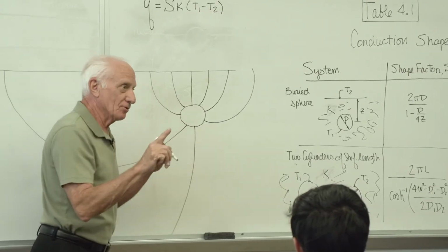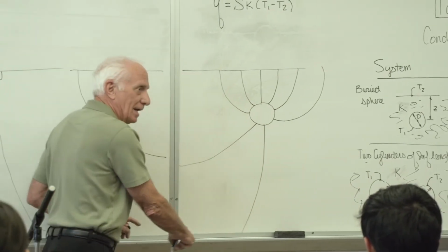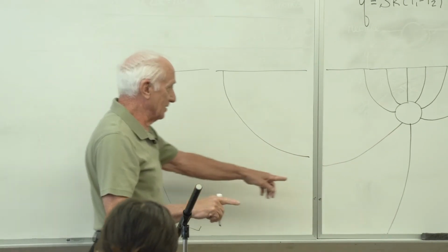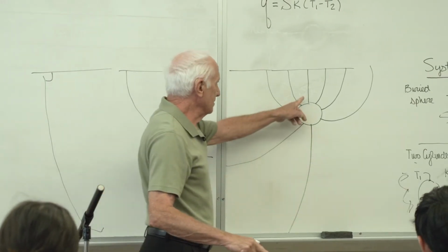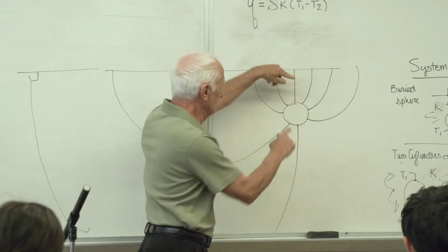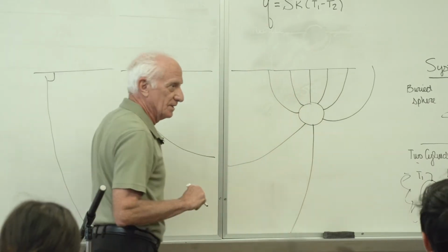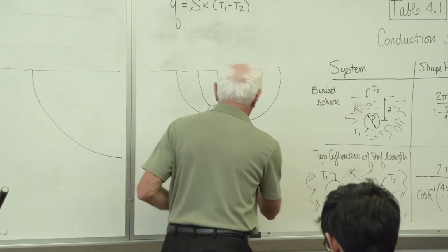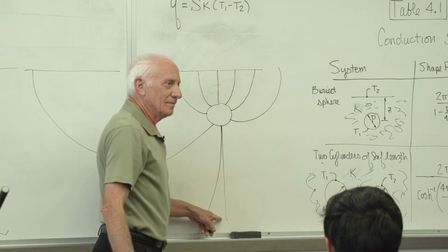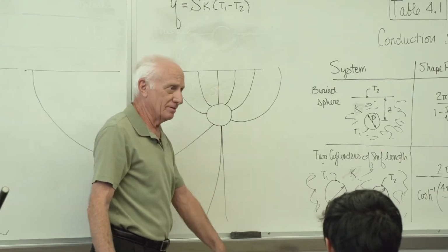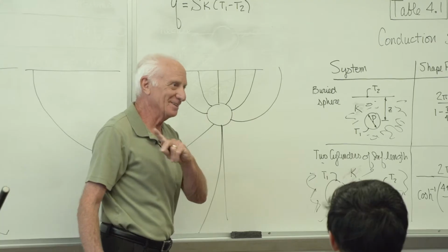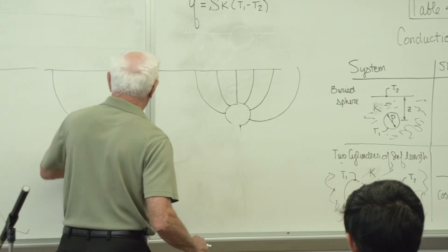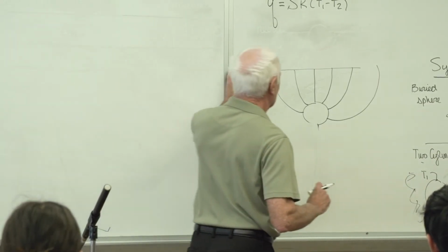But how much goes that way? Not much, because look how long that line is. And what's the resistance? The longer you have the heat go, the bigger the resistance. This line, tremendous resistance. Very little heat flows here. This line here, a lot of heat flows there. A small distance, small resistance, bam, heat goes up. So yes, it goes down. There's a line. How about this guy? I don't know, he goes to Southeast Asia somewhere, straight through the earth, and then comes up again to the soil. I don't know where. But that's the game we play. It works that way. So that's the flux plot. But yes, good question.